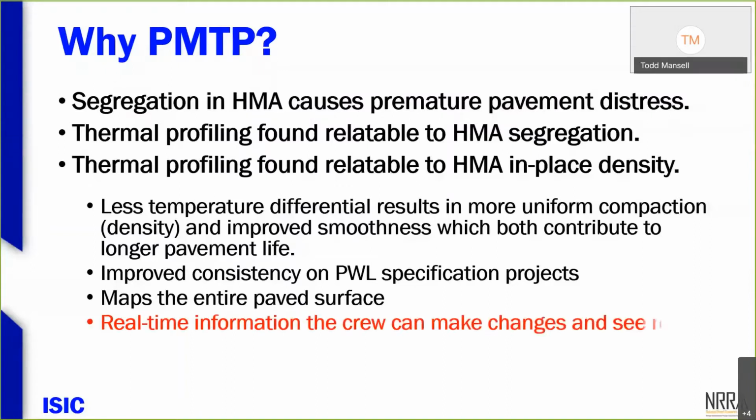What I personally really like about it is that it's real-time information. The crew can make changes and see results during paving. So we can tweak things, we can change things in the field as we're paving to improve our thermal profile or improve the uniformity of temperature of the mat, again, as we're paving. Not something we look at after the fact and scratch our heads, wondering if we have any notes on why we've got a failure in this particular area and things like that.